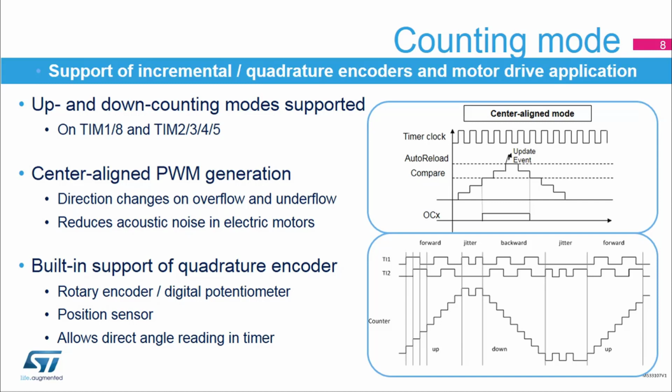For a given PWM switching frequency, this mode reduces the acoustic noise by doubling the effective current ripple frequency, thus providing the optimum trade-off between the power stage's switching losses and noise. The counting direction can also be automatically handled when the timer is in encoder mode.